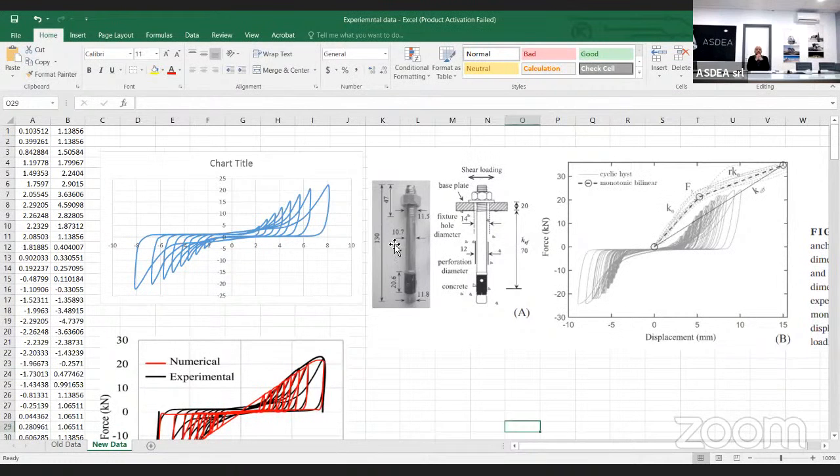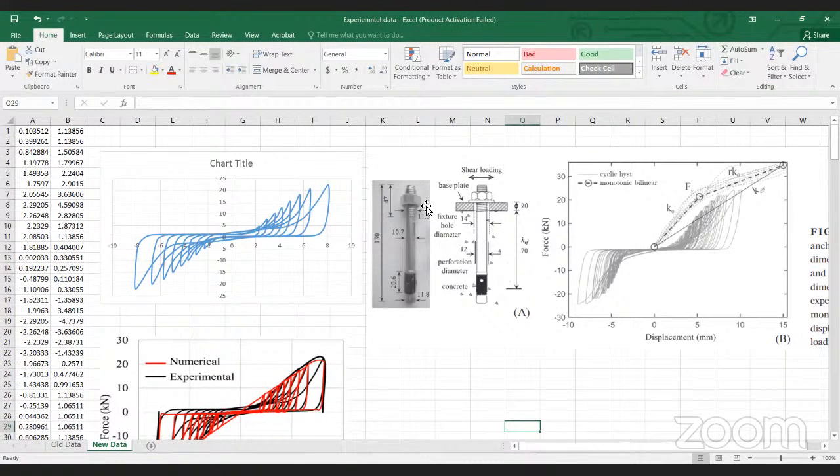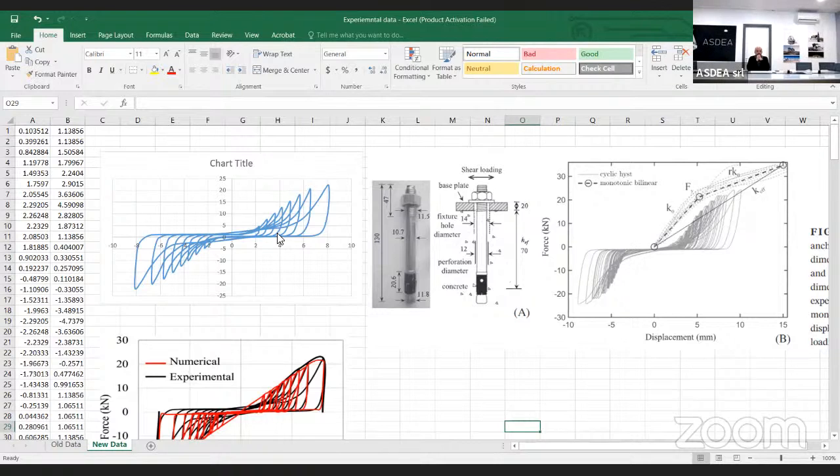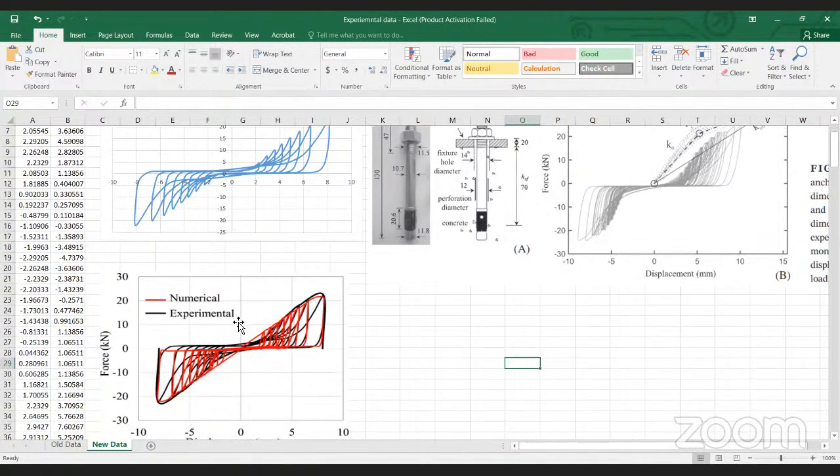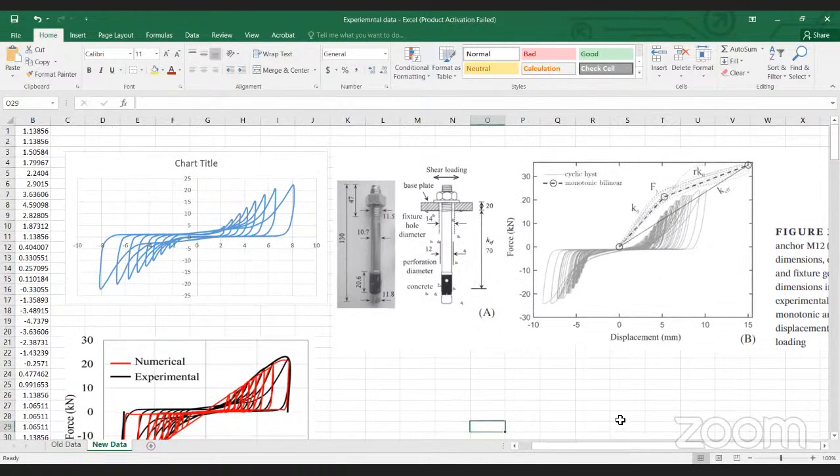Yeah. So this is like an anchor bolt. We apply the shear loading, and we find the shear hysteresis of the bolt. Now when I use the SAP2000 multilinear link element using the pivot hysteresis, I was somehow able to catch the effect, and it was working well. But when it comes to OpenSees, I was a bit blind about STKO, how I can calibrate my experimental model with this one.